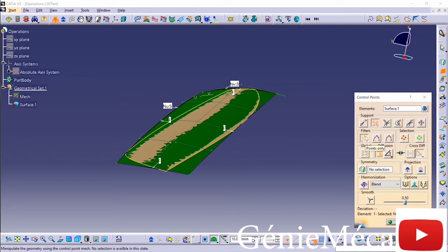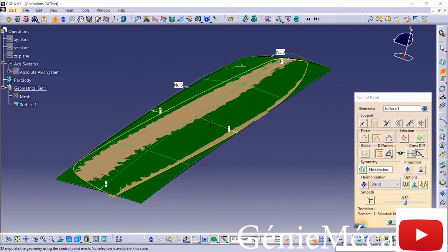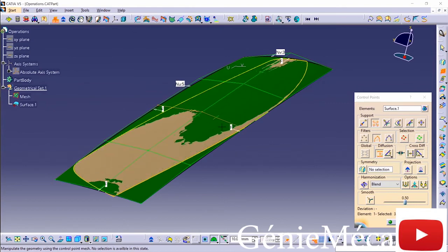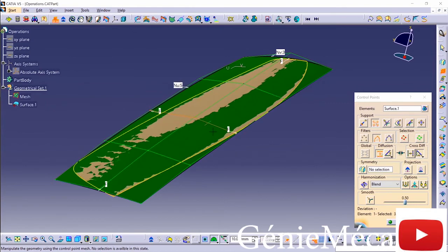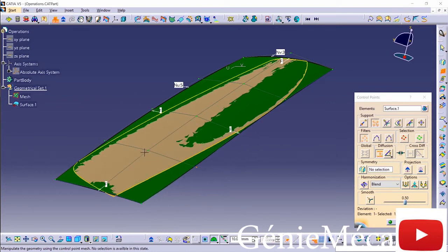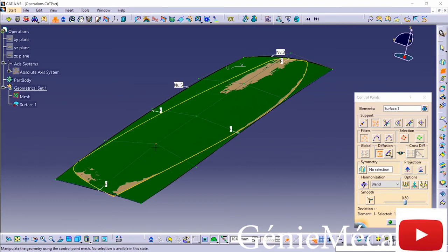And what do I want to move? One of the control vertices or the entire hull or the mesh? Now when I pick on that mesh, you can see it's the entire row, not just one of those points. And I'm causing a swing and deviation back to the original mesh. If I want to move just one of those points, I can pick point right over here, pick the point that I want, and as you can see, I'm moving just a singular point. I can do the same thing up here, and I'm moving just that singular point.